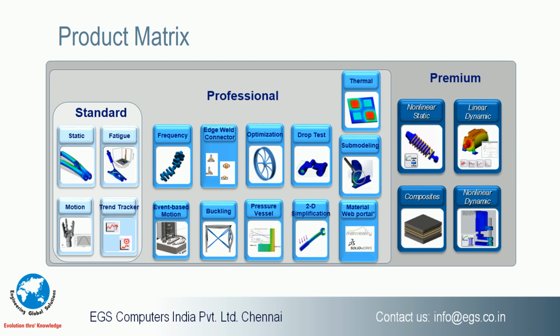And in Motion, we have time based motion analysis. Let me explain this with an example. If there is an automatic packing industry, time based motion analysis can be used there by simulating the motion of the conveyor belts and the motion of an object, to see at which station it is going to be stopped, or at which station it is going to be loaded. Not only that, we also calculate the kinematics, for example, the RPM needed for the conveyor roller to rotate to get the package into the right position.